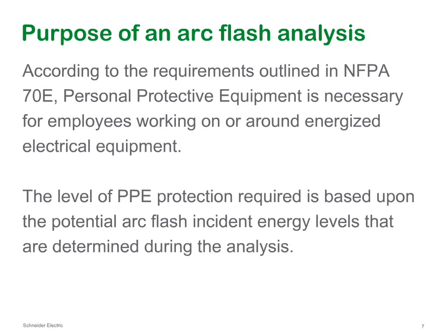So the purpose of an arc flash analysis is basically to calculate the arc flash energies and put them into a format of a label that would go on the equipment so that when the worker approaches the equipment, he has knowledge of what that danger, what that hazard is, and he can appropriately protect himself by wearing appropriate PPE. So this is, by the way, one of the last rungs of protection when you come down to the hierarchy of protection for the worker, because PPE is basically the last resort of protection.